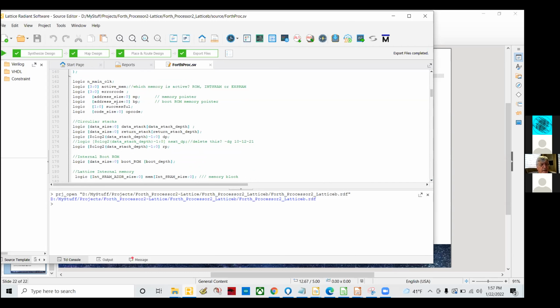Right now we have a separate memory pointer and a boot ROM pointer. We could make them the same, and memory map the boot ROM at the low side, and have the memory start above the boot ROM, or we could have separate buses. It's kind of in flux.